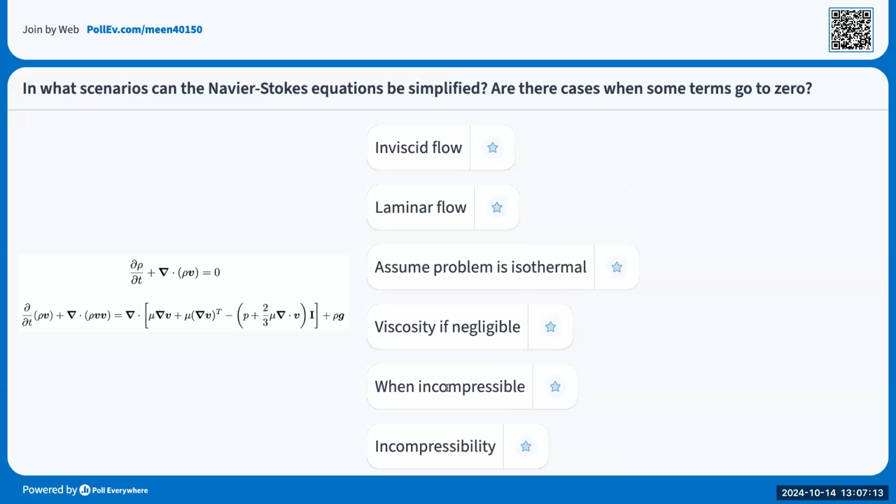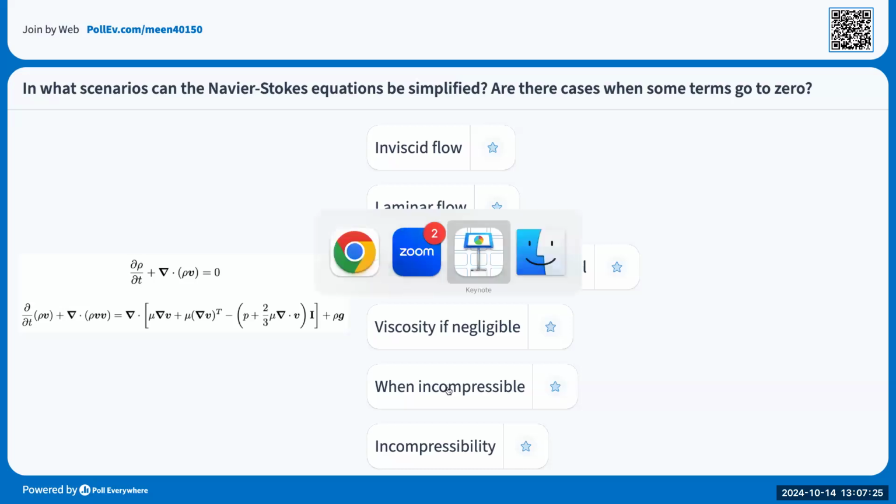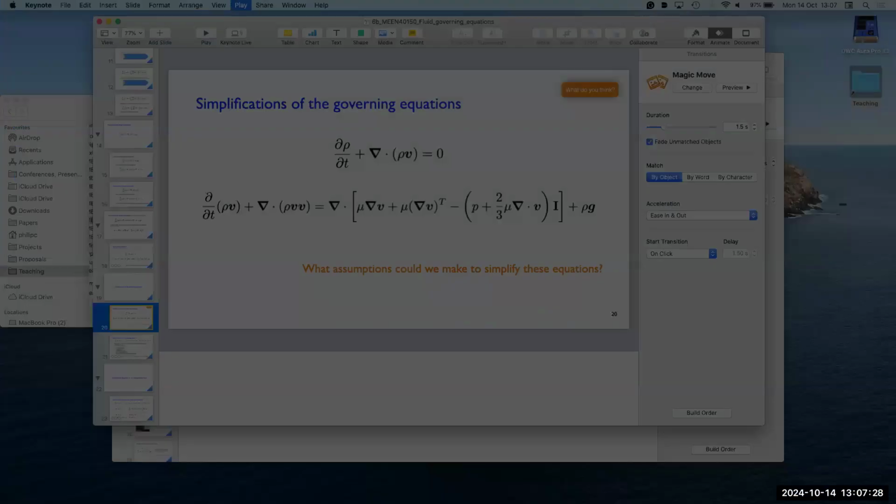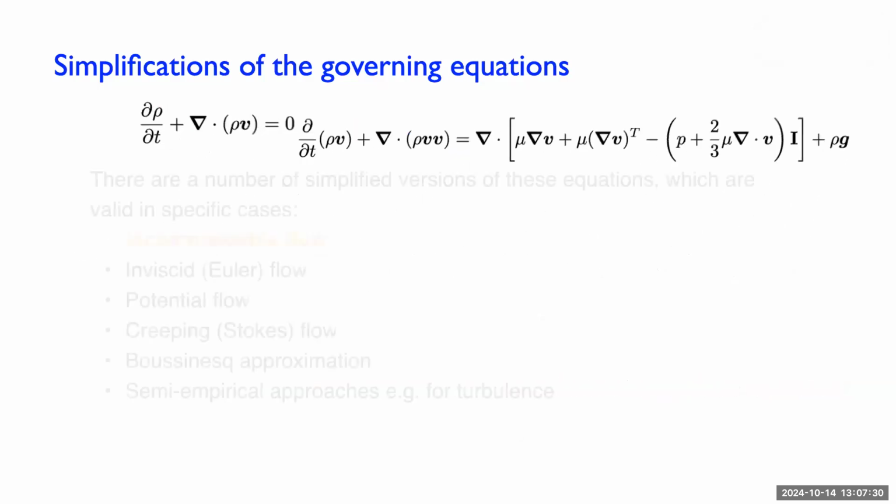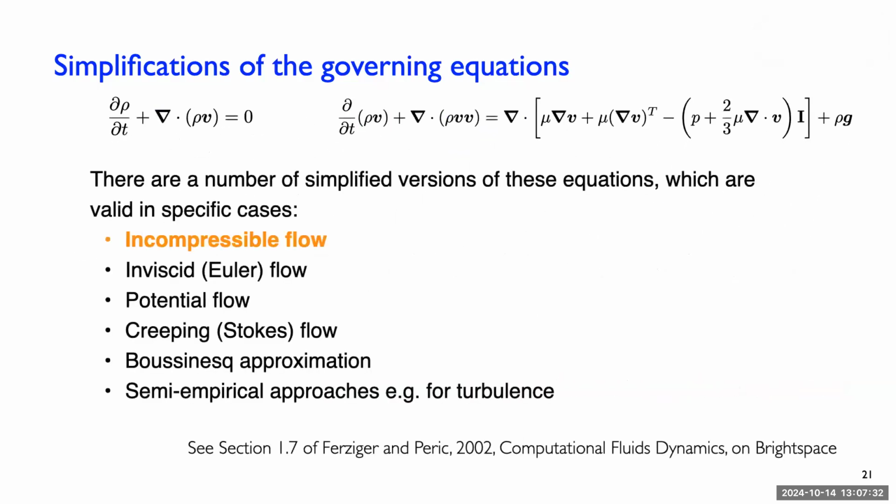Inviscid. So inviscid just means no viscosity. Yep, correct. So viscosity is negligible. Inviscid flow, they're the same thing. So assuming a negligible viscosity. Very good. Let me jump over here and go through some common assumptions. So incompressible flow, and I'm going to show how the equations change, because that's going to form the main CFD approach we're going to take in this course.